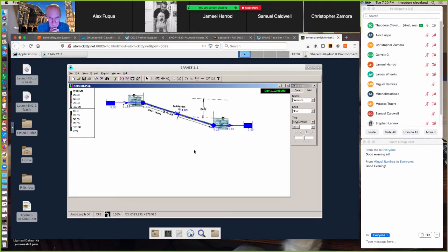The pressure at both the upstream and downstream node, each of which are 10 feet below the water surface, both 4.33. So in this particular setup, the flow is entirely gravity flow. That's kind of interesting. You'll notice the pressure in each of the reservoirs is reported as 0.